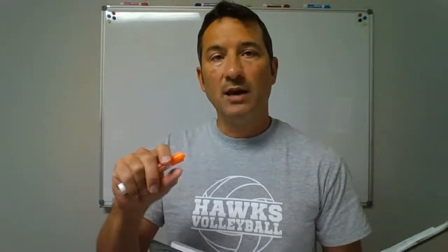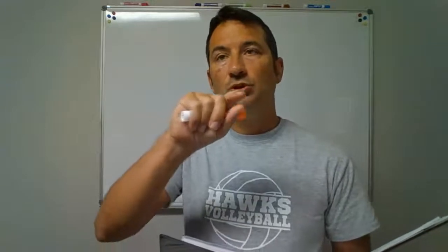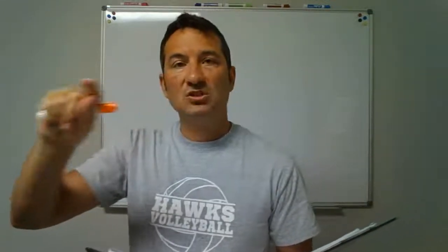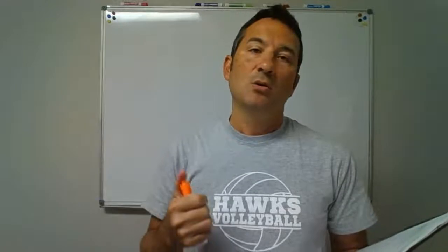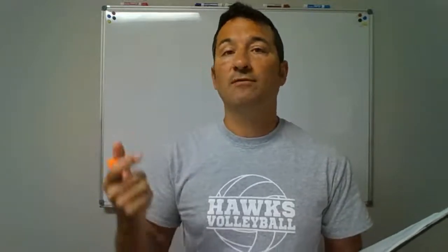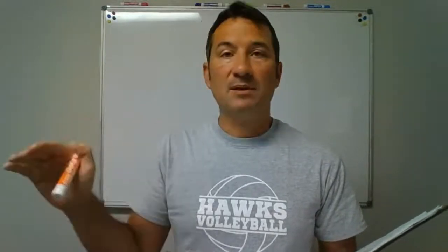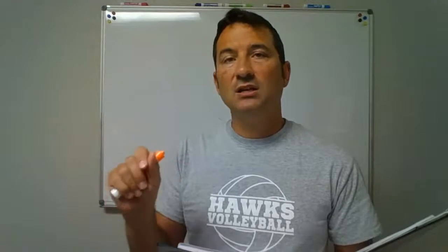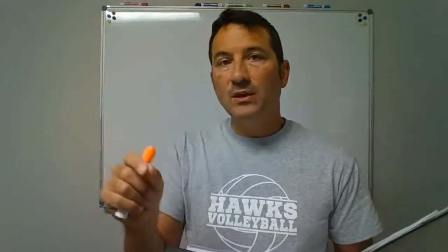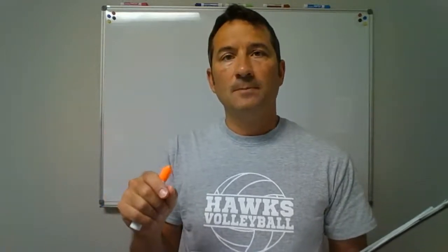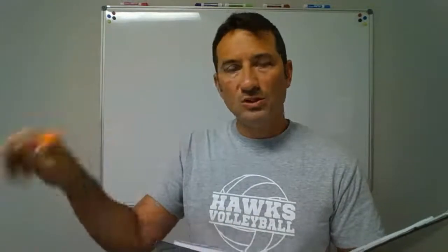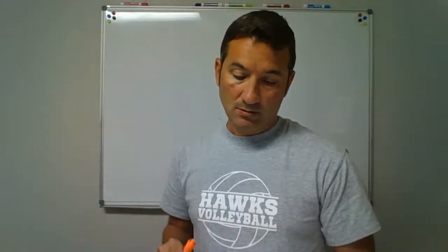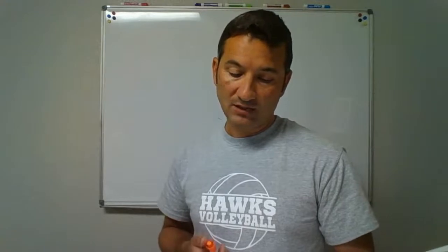If you remember installing the pipe under the house, you saw information stamped along the side: the pressure ratings, the manufacturer, and the ASTM numbers that say what's approved. You've got to have that pipe identification on there.